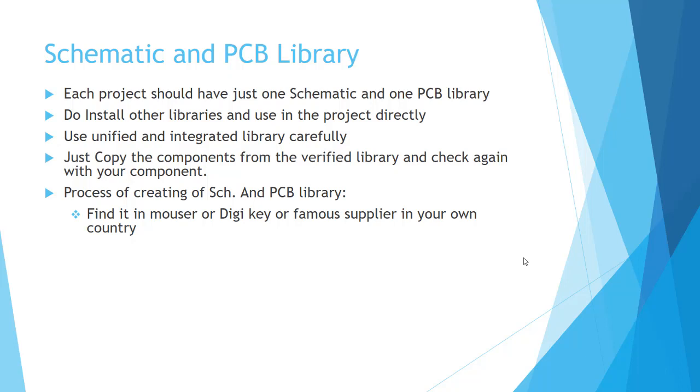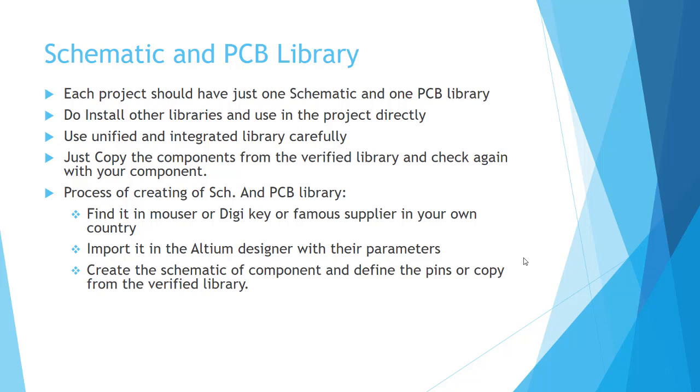So in your schematic library, create a schematic library for each of your resistors, capacitors, inductors, and other components. Then after you copy the component reference, import it into Altium Designer with their parameters, and then create the schematic of the component manually and define the pins, or copy from a verified library, for example your previous library or some integrated libraries that are available.